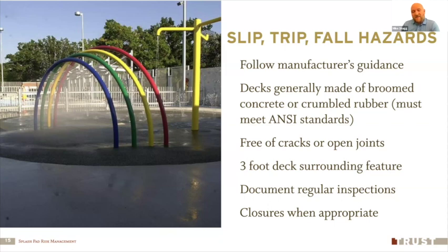The flooring has to be free of cracks or open joints. This time of year, before you start up those splash pads, is a great time to make sure that your flooring is free of cracks and open joints. Have the maintenance folks go around and put caulk or waterproof sealant or something in the cracks and open joints, so that we don't get those toe grabbers that kids could really stub their toes on and lacerate feet and toes.